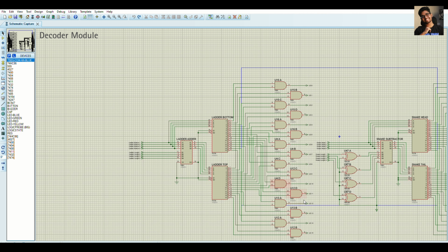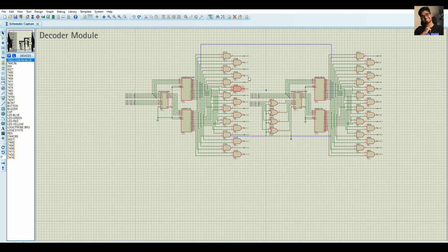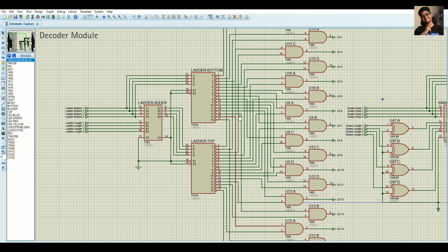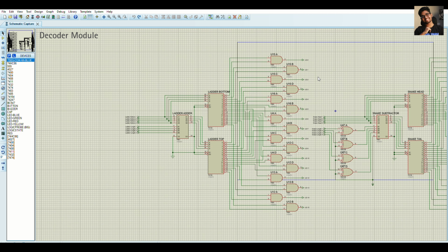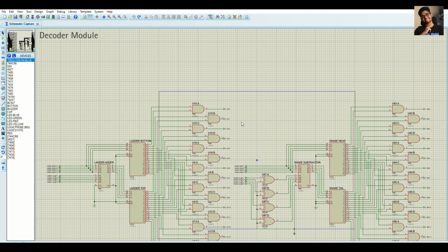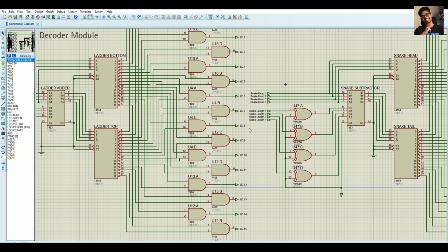We know that the ladder bottom and ladder top are not the same number because we have ladder length as a value. If ladder length were 0, then the ladder bottom and ladder top would have given the same output signal. So as ladder length has a value and ladder bottom and ladder top are different, among the 16 AND gates, 0 is supplied in one of the inputs of each of two gates. All the other 14 AND gates get 1 as inputs. So when the complete calculation is done, only 2 of the AND gates give a 0 value, while the other 14 give us 1.